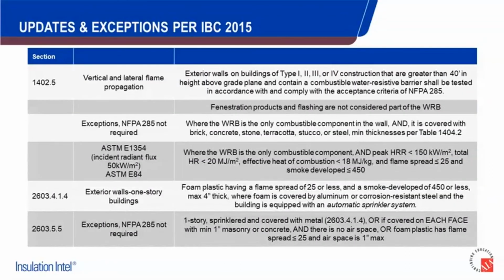Couple other things to mention here. Again, a whole slew of exceptions came out in the code in 2015. That was a bit of a pushback to the introduction of WRBs in the 2012 code. I'm not going to go into these in painstaking detail, namely because almost all of them just got rescinded in the 2021 IBC. So there was a handful of exceptions that got put in related to WRBs mainly. Just some pushback there related to height, the actual embodied energy in that material, et cetera. But in the latest version of IBC, the 2021 code basically rescinded all of the most common exceptions that were out there.